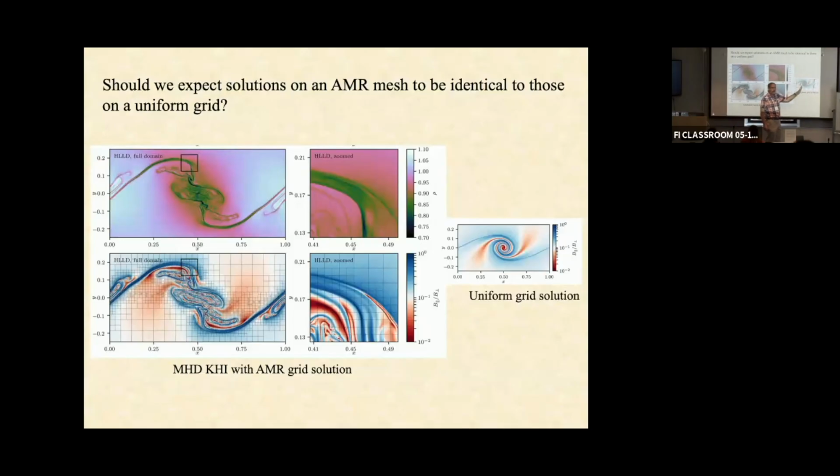There was only the initial sine wave perturbation, which gave you one roll up, and nothing else was excited, and so there were no other instabilities. But with an AMR mesh, you have all these fine coarse boundaries, you have prolongation interpolation, you have round off error inevitably, and the round off error is not uniform everywhere, and so that's a perturbation. And so you seeded a physical instability, but the seeds of that instability were all numerical.